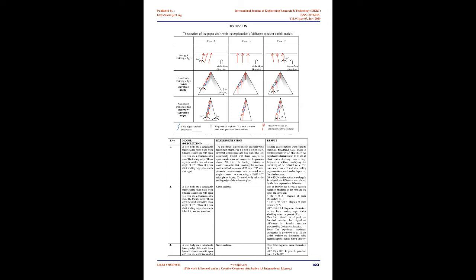It is designed in such a manner that it can demonstrate the flow and noise measurement values carried out at different surfaces. The experiments were carried out in an open wind tunnel of Yazd University. In the present wind tunnel, the centrifugal forward blades type fan creates low broadband noise. Microphone dimensions are 2.5 mm in diameter, 2.5 mm in height, with a circular sensing area of 0.8 mm.